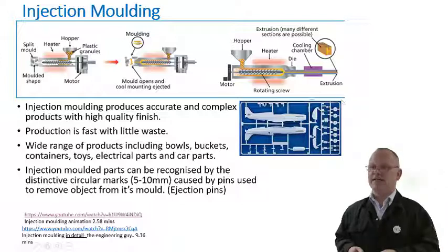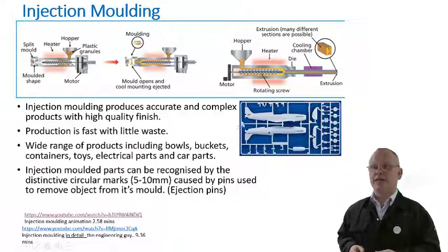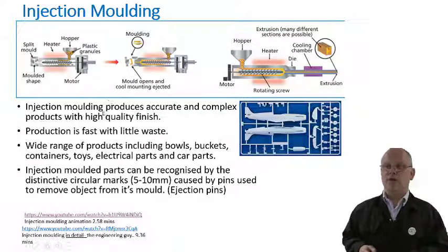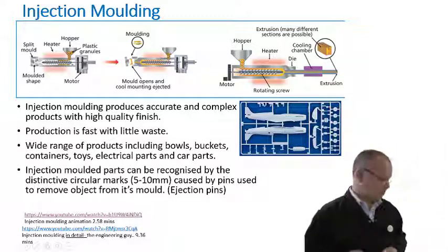Another favourite example of mine is the Airfix model parts, because this frame is also how the plastic gets through the whole part. Okay, so it might be injected at this point, but it then flows along here and starts to fill your mould through these gates until the whole thing is loaded up. So you can see the sprue in action. It happens to also make it a really nice frame for model making, but that's a good example. So it would be injected at one point. I'll show you an example of how you can look on a product and see that it's been injection molded.